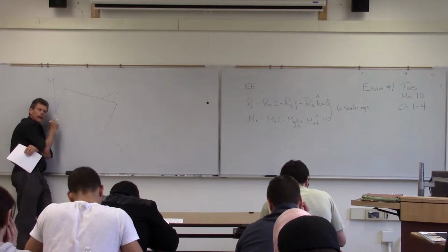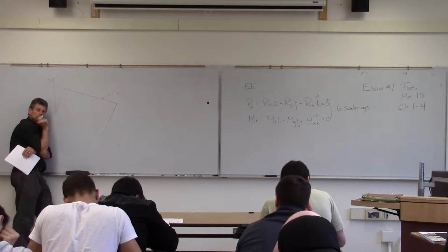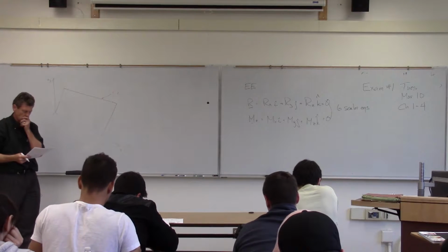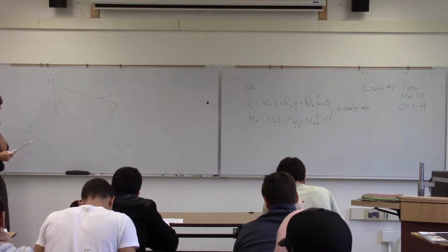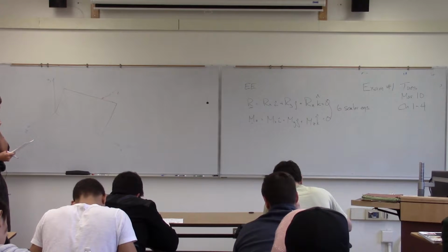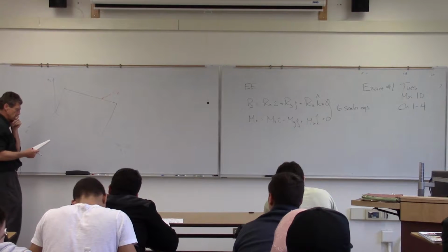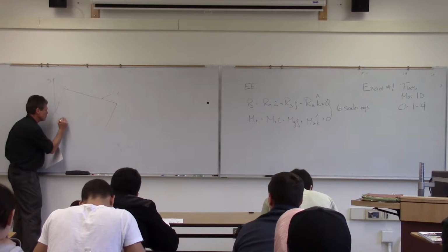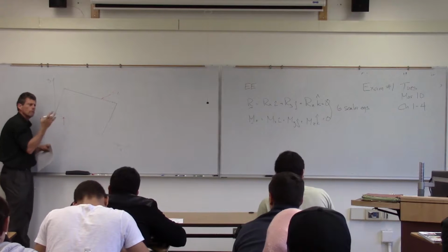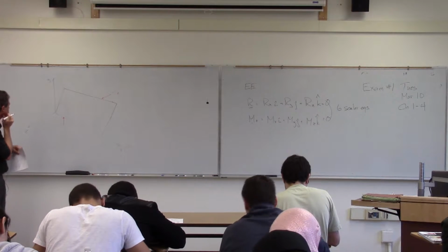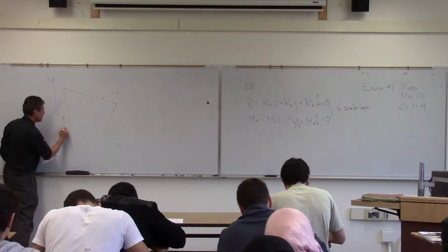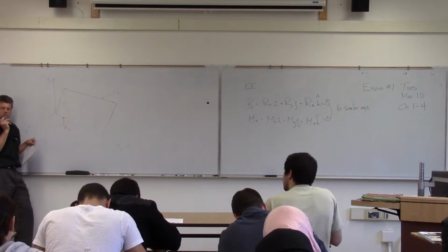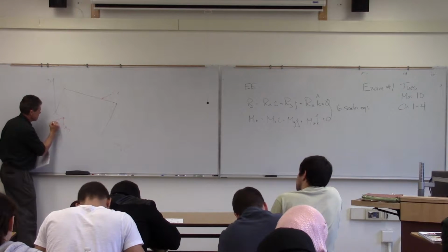Let's think about A. Another perpendicular force. It's restricted in everything but rotation, basically. It's like a pin, but it's three-way. Okay, so it's going to keep me from going through the ground, right? So I'm going to have a force, and I want to try to keep it in components so I can develop my equations there. So there's going to be an AY component. Is it going to allow me to slide in the z direction there? No. So I'm going to have a force there.